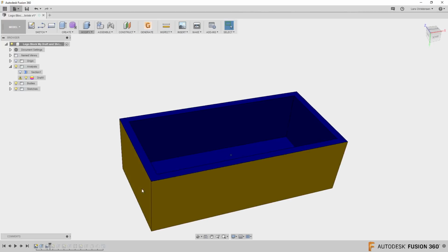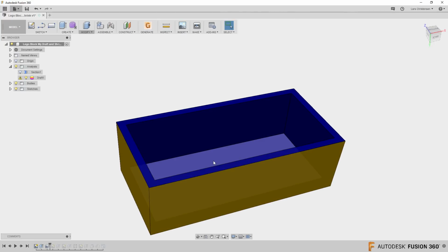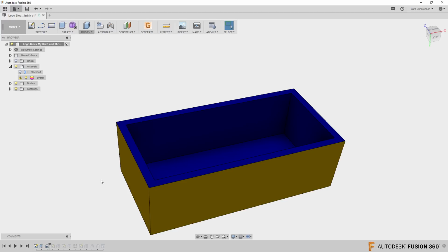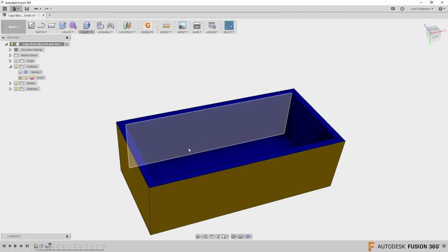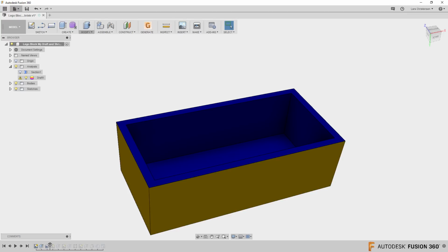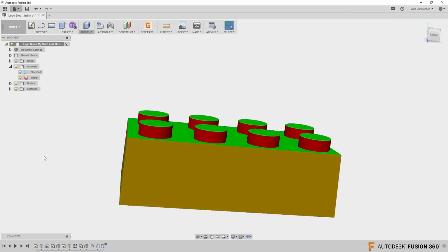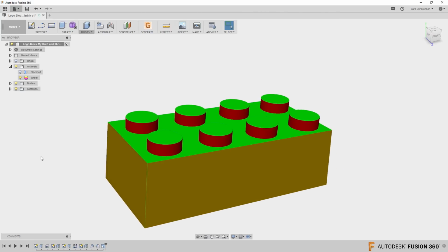We've used that before, and gave it a thickness, and that would emulate the outside. So it's offsetting the outside wall, meaning you do get that 2 degrees on the inside too. So that can make your life easier. So one way to add draft is to add it right inside of the feature.